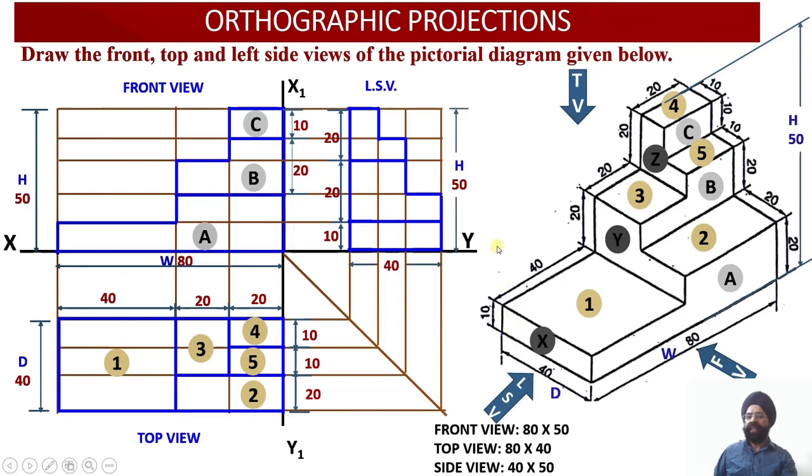Now please check. These dimensions I told you earlier, these are there only for your reference, so they are not required later on. So I have removed these dimensions. I have got these surfaces X, Y and Z. X, Y and Z are also true shapes because these surfaces happen to be parallel to the profile plane. And another thing we can note over here, the total dimension I had mentioned as 50, whereas the breakup is also mentioned over here, 20, 20 and 10.